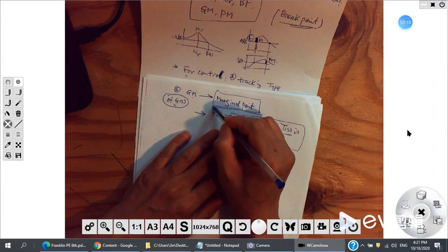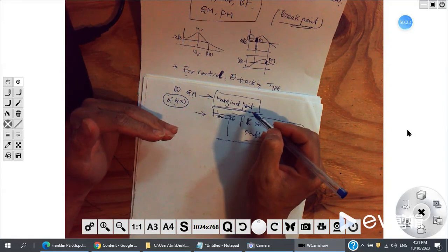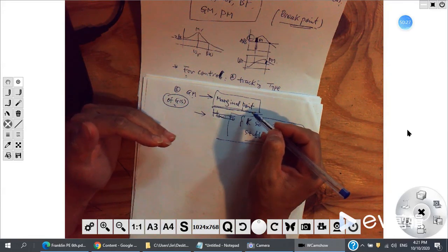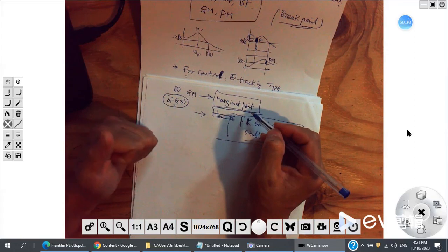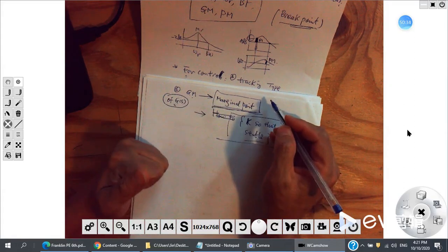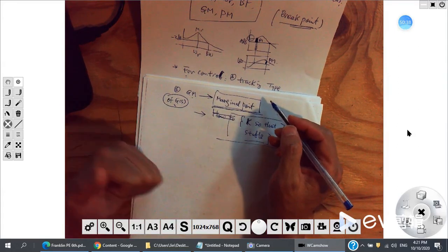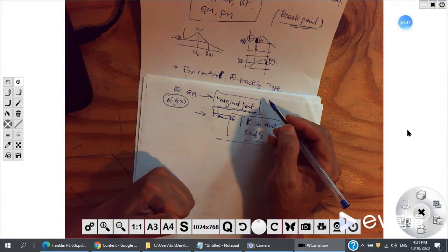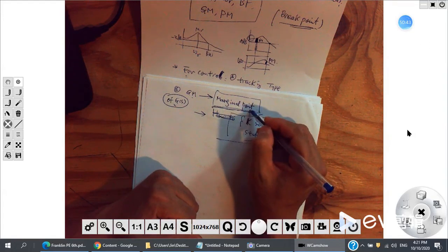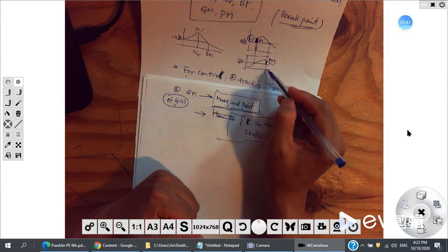But when K goes across the marginal point, what will happen? The system will change from stable to unstable, or the other way, from unstable to stable, right? Two directions. Both cases are a marginal point, but just by checking the phase margin and the gain margin, sometimes you can make a decision, sometimes you can't.